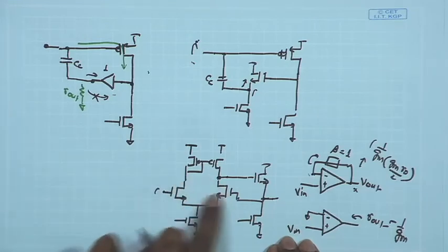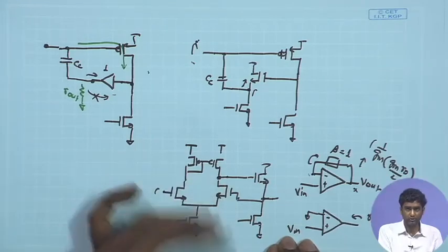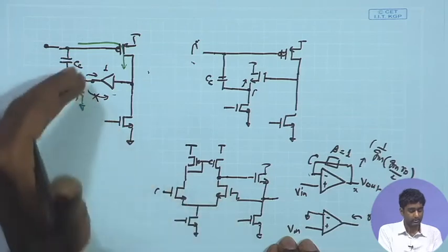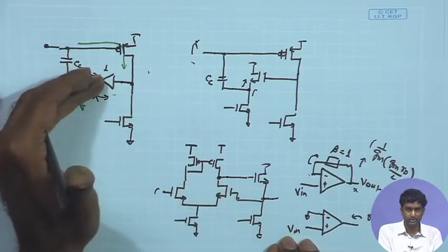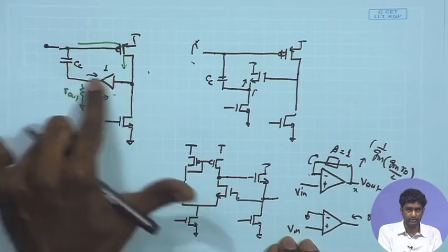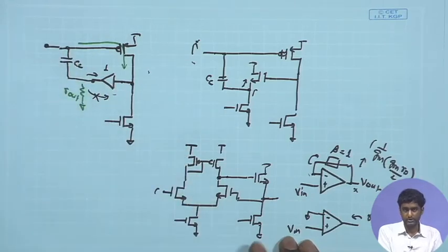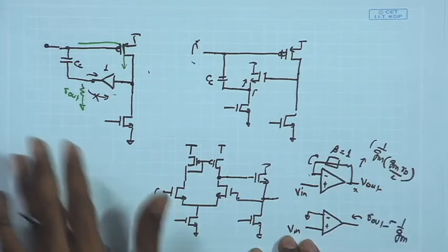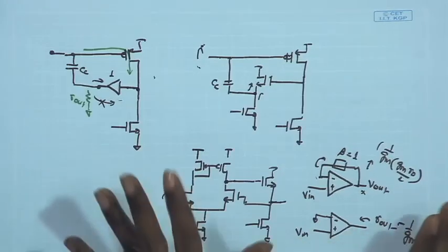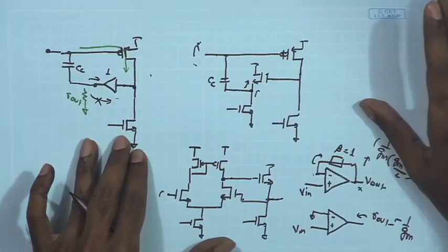We can achieve similar bandwidth at the cost of lower gain and still achieve low output impedance and a good buffer functionality for this particular unit, so that the effect of the 0 is getting eliminated. So, this is one particular technique which we can employ in our design to arrive at the cancellation or elimination of the 0. Now, let us look at the second one.